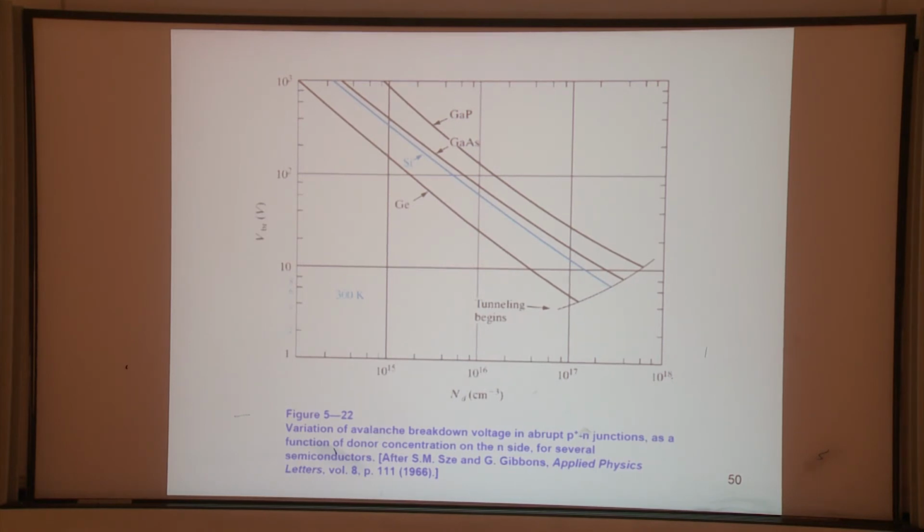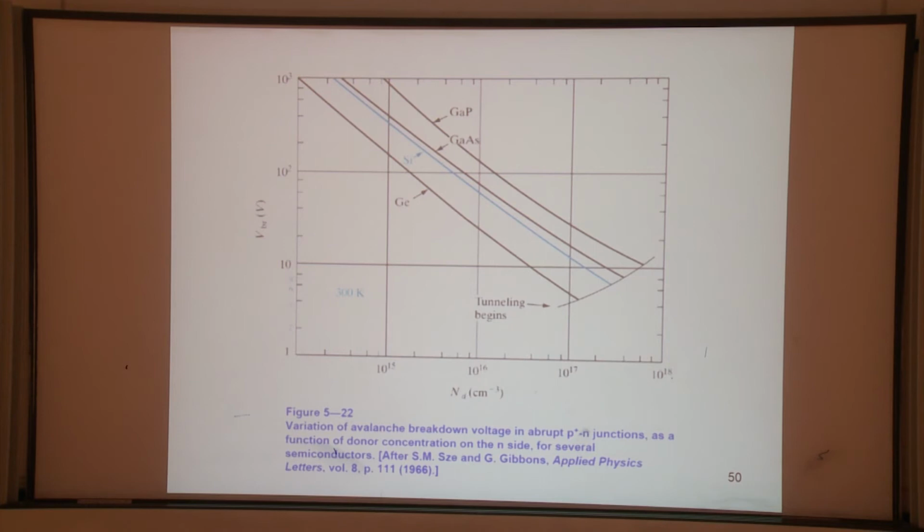Okay, so this is the diagram for 3 kinds of semiconductors for the breakdown current. Usually this diagram is for which kind of breakdown? This is for avalanche breakdown because the range for doping is very low. It's very low. Let me just give you an idea of a doping level. This is in the unit of per centimeter cube. If you dope the material 10 to the 15th per centimeter cube, is that a high doping or low doping? Low. 15 sounds very high, right?